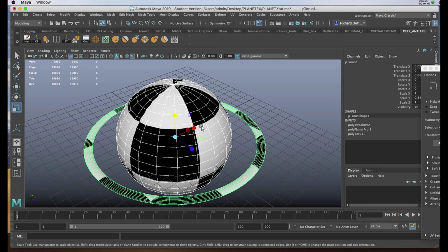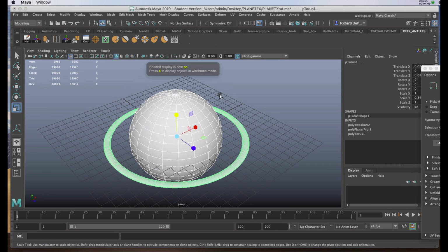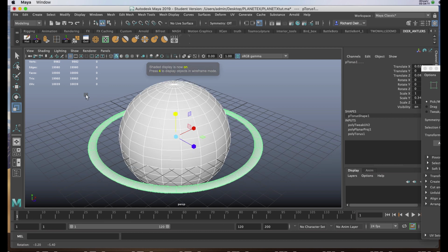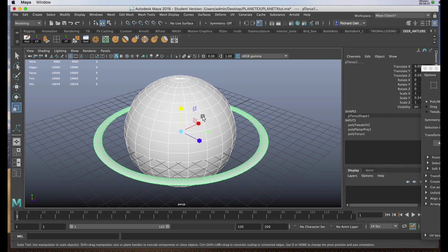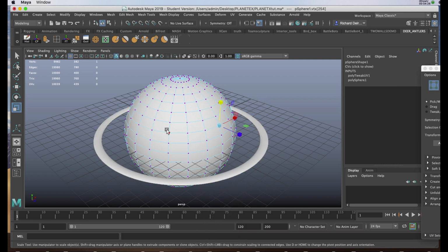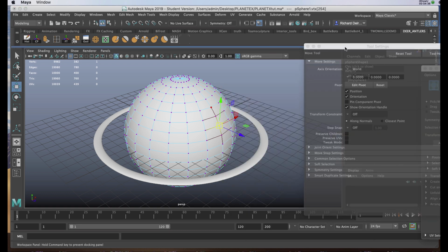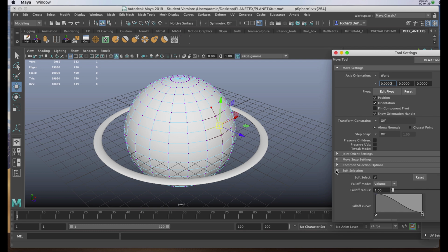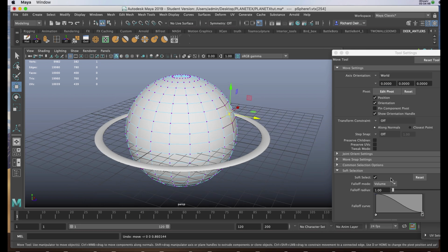I'd like this to be a little bit more organic. So I'm going to use a tool we've used in previous projects. I'm going to use a soft select with the Move tool. I'll right-click, choose Vertex. Selecting a vertex, I'll hit B on the keyboard. Now in order to edit that, I'll double-click on the tool itself on the toolbar to adjust the amount of the soft select. Opening up the soft selection tab, I can go in and change the number to something else if I want. It's very subjective at this point, so I think what I'll probably do is just bump this up a bit.